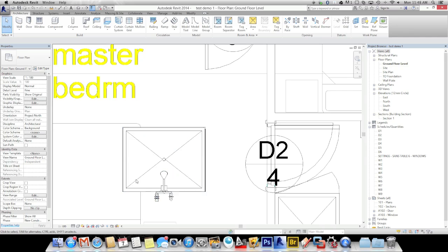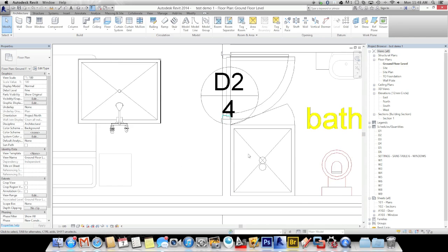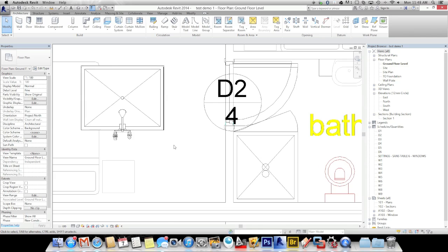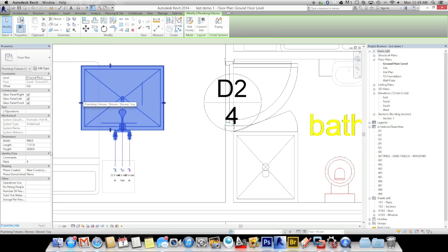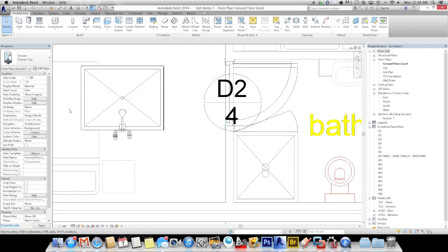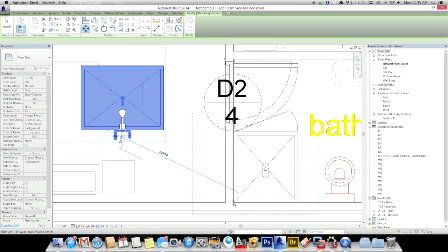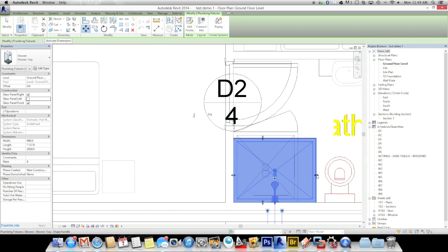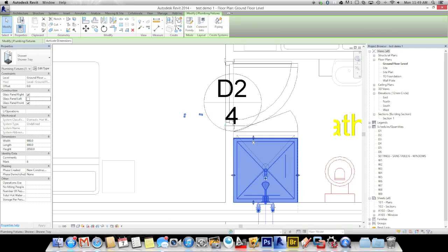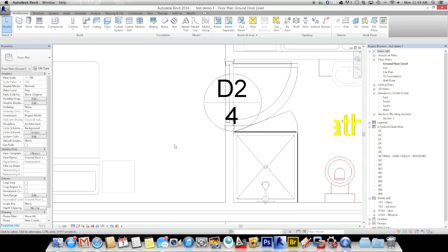How that works is, let's say for instance, we want to insert it into this corner. You select it. You switch off left panel. That panel is now switched off. You go MV for move. Sorry, you select it first. MV for move from that corner to that corner. And then you just use the grips to get it into place. There you go.